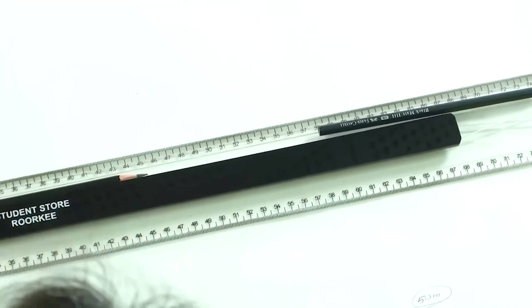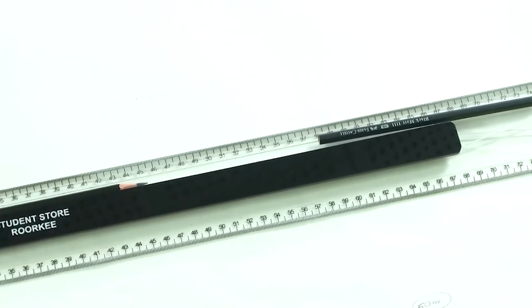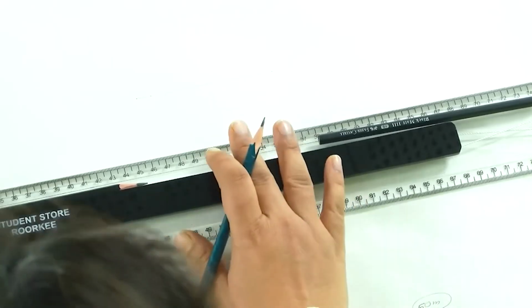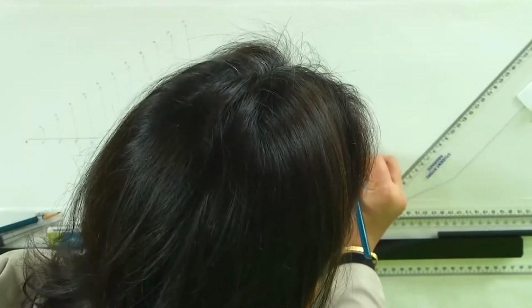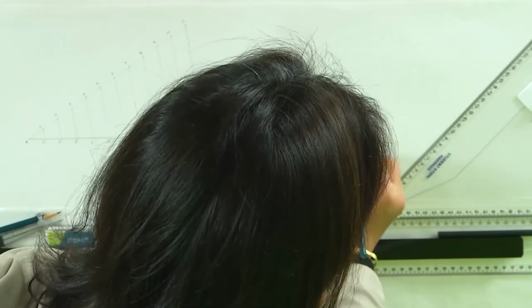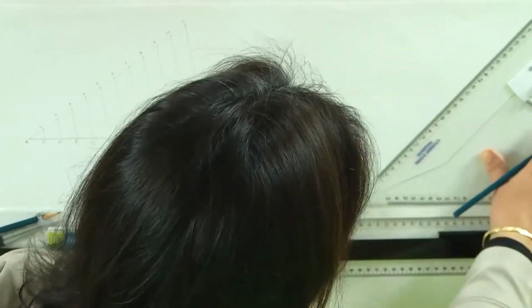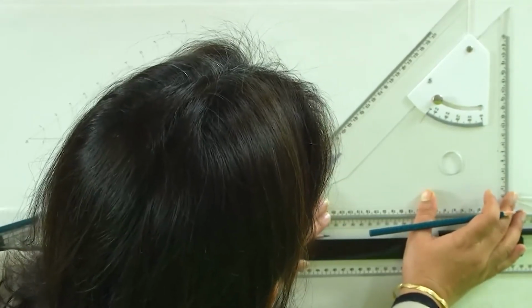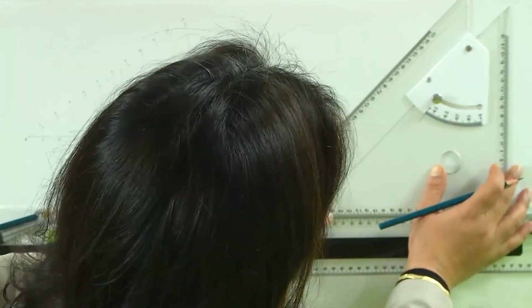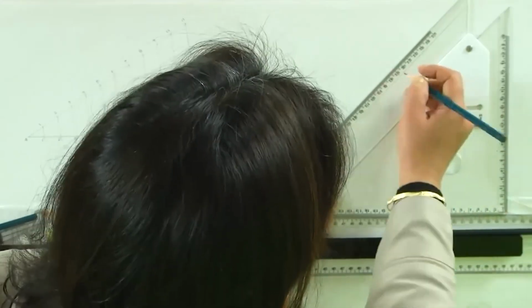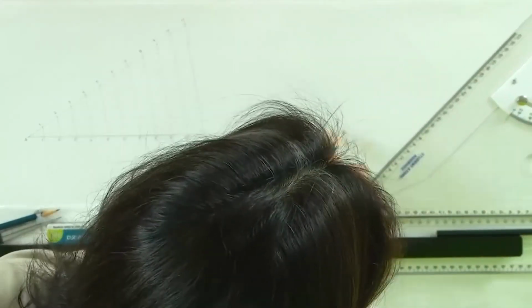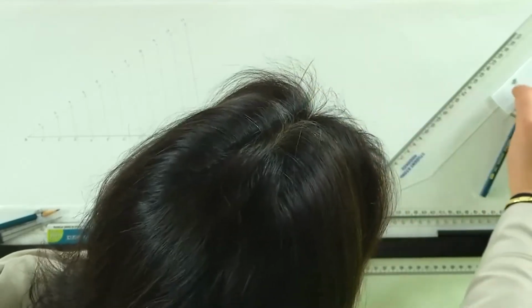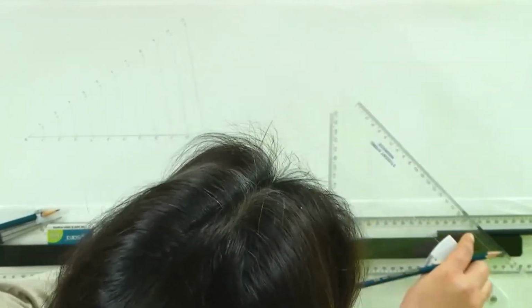Now, this one we will divide into 10 equal parts. I have already divided this line into 10 equal parts, but the very first division we will have to divide into 10 equal parts. To make those 10 divisions, I again draw a line at an acute angle, and I am again taking here a 10 centimeter line. It could be anything, but just for convenience I have drawn another acute line here with 10 divisions on it, and now I will connect it.